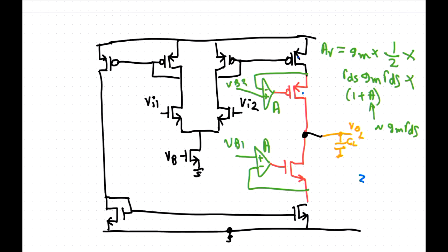So the reason why I haven't seen this before with the gain stage amplifier, like a lot of textbooks, I guess those aren't real world circuits, but most real world circuits have this sort of structure. This is an excellent amplifier, so yeah, for on-chip circuits, absolutely you could. A lot of the papers I read just have VD that don't drive the gates. Yeah, but driving the gates gives you better control and a high output impedance.